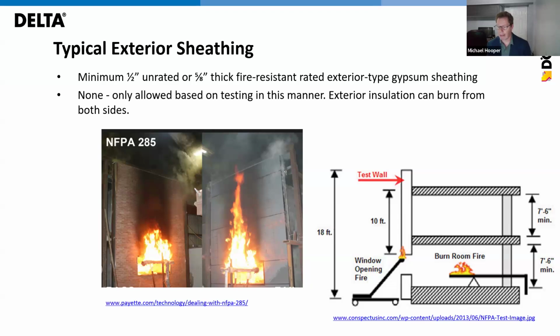Now, ACM walls, general consensus is they easily melt, they ignite, they spread flame. If you pass with an ACM, fire consultants can write engineering evaluations that any cladding that is less combustible can be substituted without having to perform a full NFPA test. ACM testing is usually connected to polyiso insulation manufacturers who usually conduct their own testing as a worst case scenario.